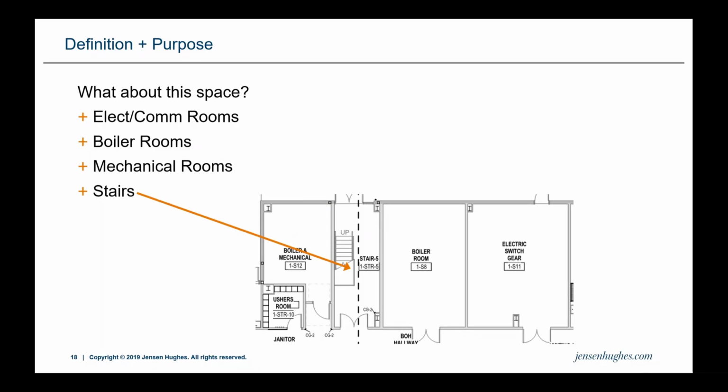Now, stairs, again, are much like elevator cabs. They differ from small buildings versus high-rise. We wouldn't put speakers normally in a stairwell in a small building, but in a high-rise, we frequently do, every third floor or something like that, so that we can have manual voice capability into the egress stairs. So that's something to consider. And stairs create quite a challenge, right? Because really they're a series of concrete boxes, which makes it quite difficult to achieve intelligibility.